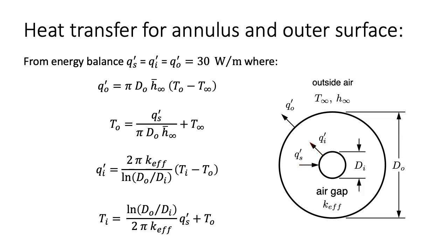Second, we perform an energy balance on the outer glass cylinder. Based on this, the convection across the annular air gap must equal the convection from the outer surface to the surrounding environment. Alternatively, if we use a resistance analogy to model this system, the two thermal resistances are in series and the current or heat transfer through each is the same. During normal operation, when water is flowing through the pipe, most of the solar radiation would instead go into heating the water flowing in the tube, and the whole system would operate at lower temperatures.